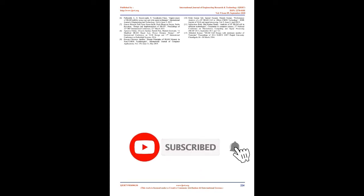1-bit 6T SRAM schematic. 4. Results and discussions. The functionality write/read operation of 1x1, 1-bit, 6T SRAM cell is shown in Fig 10. When word line equals 1, write/read operation takes place. When word line equals 0, hold state as shown in Fig 10. Write 1 and write 0 is performed during the write operation. Read 1 and read 0 is performed during the read operation. 1-bit 6T SRAM write/read operation.